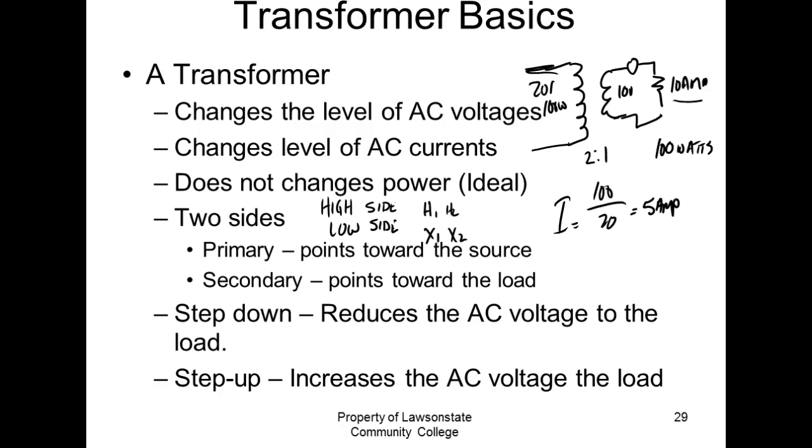You buy one from Radio Shack, they'll say primary and secondary. Step up increases the AC voltage, but the current is lower than the primary, right? You understand? If we step it down, then the secondary current would be higher than the primary. But what sets the current? The load.